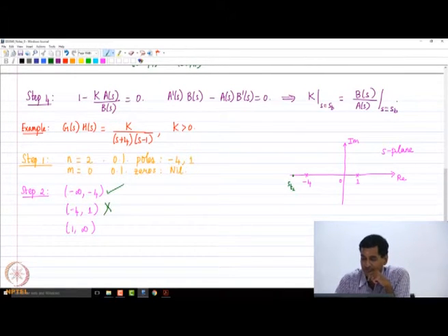No, right, because if you take a test point s_T2 in this region and look towards the right, you see that there is one real open loop pole to the right, that's odd, right. So that criterion is not satisfied, so it doesn't lie on the root locus.